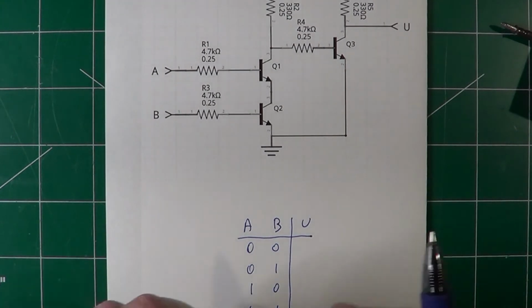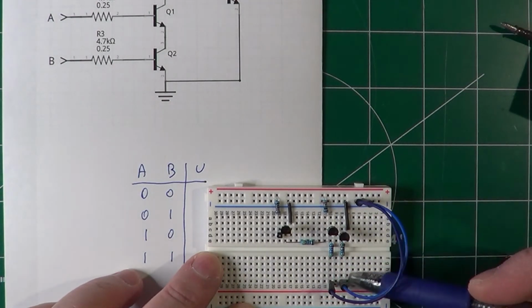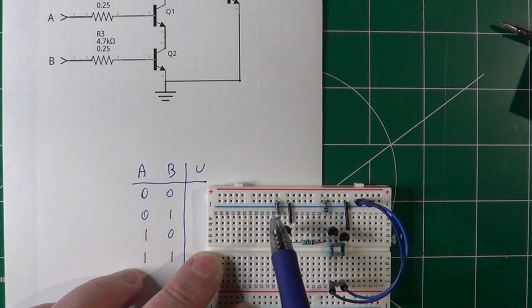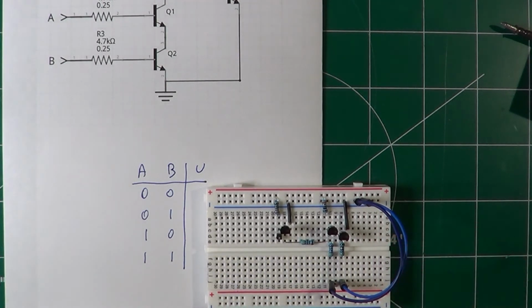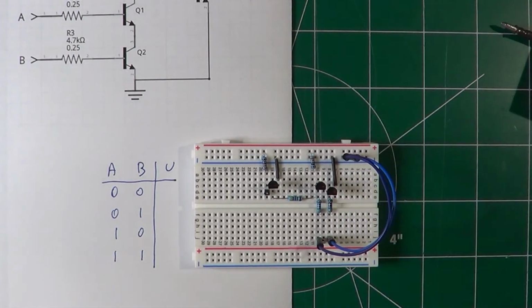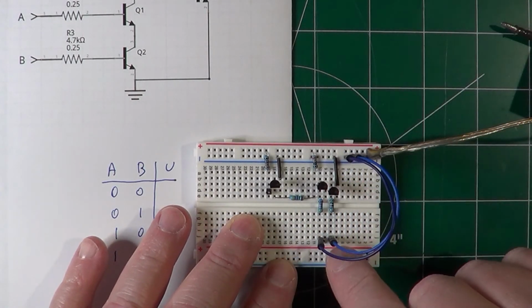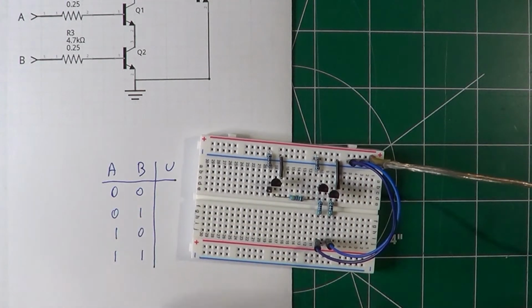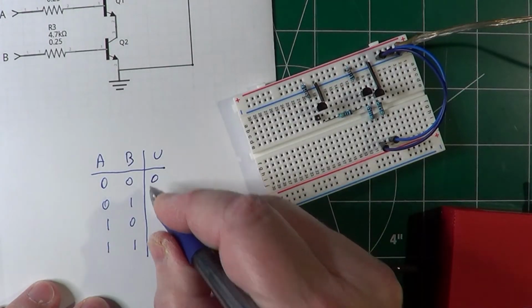Here is the actual circuit. On the right, you can see basically the same circuit we built as a NAND circuit, but its output goes now to the input of the NOT circuit built on the left side. This pin will allow us to read the output. So let's now power up the circuit. These two wires are the inputs of the circuit, and currently they are both connected to ground, giving to each of the two inputs a logic 0. Let's now read the output, and it is a 0.